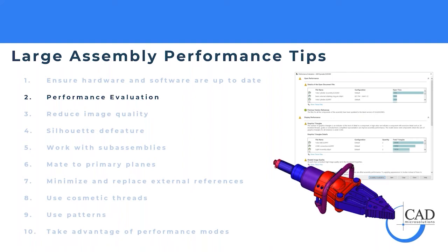But let's take a look at something like that screw at the back or the handle that both have pretty high graphics triangles, even though there isn't necessarily that much going on. This is a situation where I would potentially come in and diagnose and really look at those components and start to reduce the number of graphics triangles on them to improve my assembly performance.